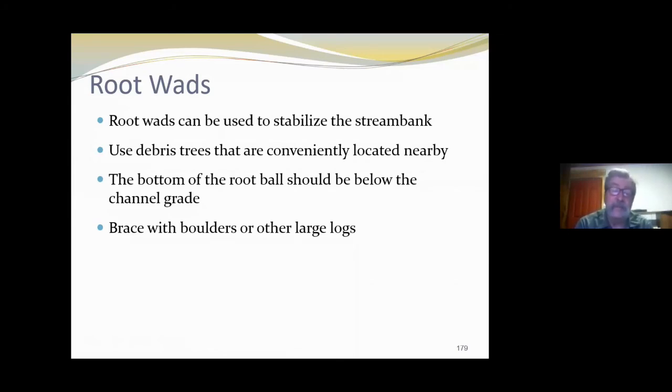And if you're placing any of that material, remember that it is floatable. If it does get exposed to a lot of those flows, it could be ripped out and wind up clogging up a bridge or culvert downstream. So you want to anchor them pretty much with large boulders and rocks.